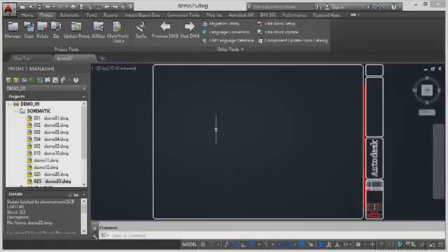It's also just that little bit safer because all the information's all in one place and you haven't got to think about 3 or 4 different workflows to get everything to work. This way, you just click on new drawing and put the data in. Job done. When you click on OK, it's linked to the project and all the data's in the right place. Whereas the other one, you've got to create a new drawing, save it, you might save it to the wrong project, and then you've got to link it, and you might link it to the wrong project. You don't know. This way, it always links to the current project when you click on New Drawing there in the Project Manager in AutoCAD Electrical.